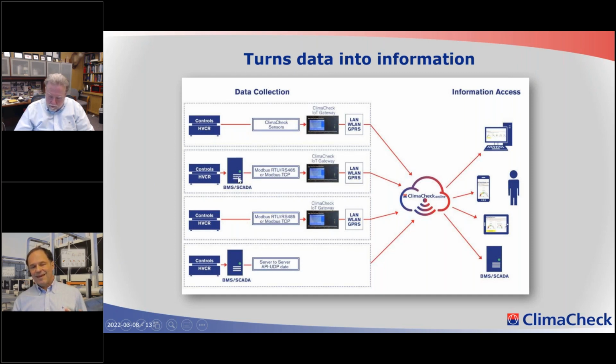So it's essential then to use this in a good way. And there are standardized protocols like Modbus, BACnet, and this type of protocols. So you can extract the data to a gateway that transfers it to the cloud. And then the result can be returned to the gateway and read by the BMS system. Of course, the gateway can read from controllers that are Modbus capable.